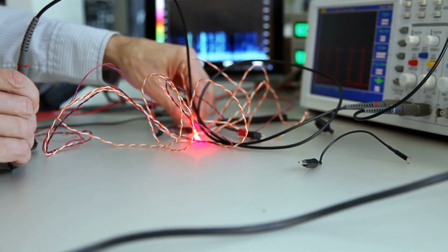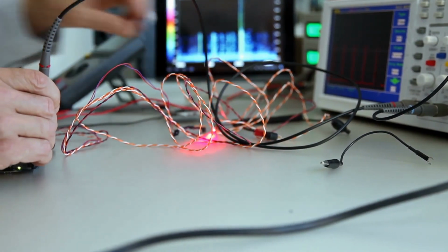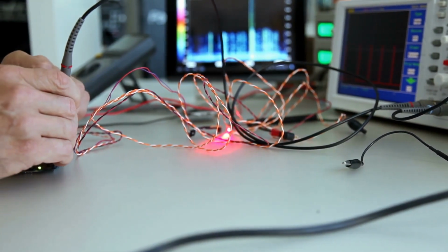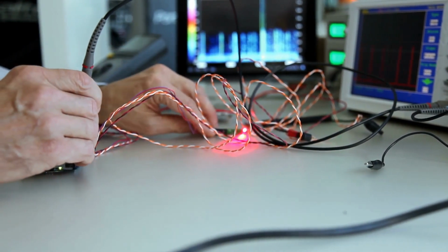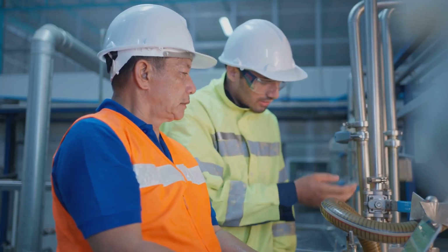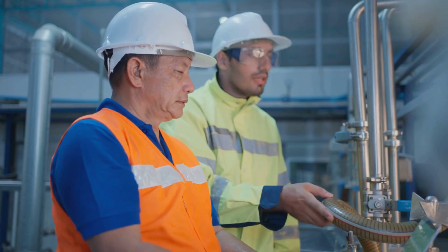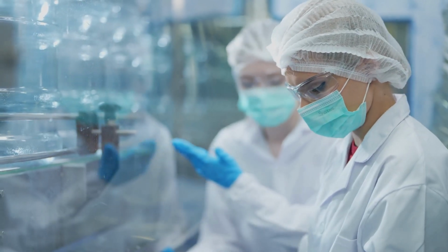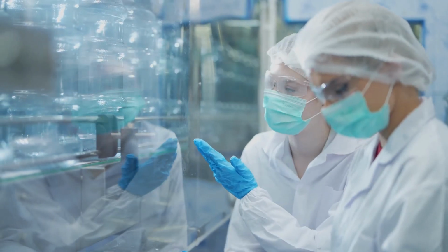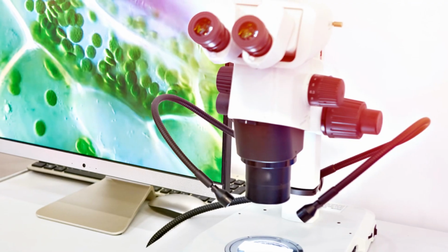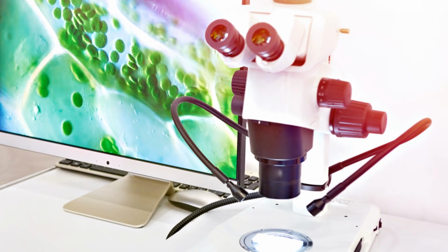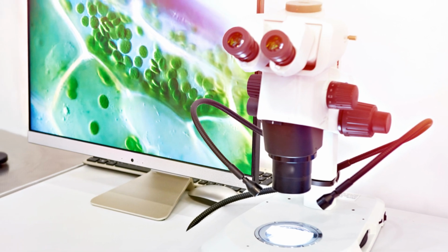To troubleshoot these issues, start by checking for any potential sources of electromagnetic interference and ensure your encoder is properly shielded. Regularly inspect the mechanical components for any signs of wear and tear and ensure they are correctly aligned. Lastly, keep your software updated and perform routine checks to ensure it is functioning as intended. By addressing these common problems, you can prevent errors and ensure accurate counts in your packaging process. Remember, a well-maintained encoder system is crucial for the smooth operation of your application.